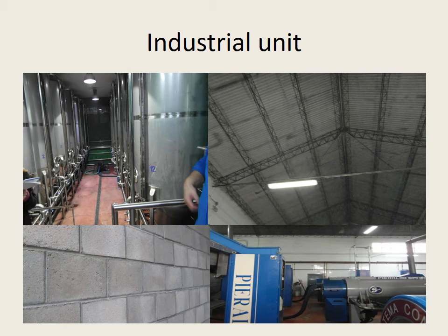Both parts have concrete floors in order to facilitate cleaning and give a solid support to the machinery. The walls of the enclosed area are built with prefabricated blocks in order to keep the stored oil at the correct temperature. The biggest construction necessity is to settle the storing area for the huge weight of the silos, the isolation needed to prevent climate disorders, and the drains in case of leaks.